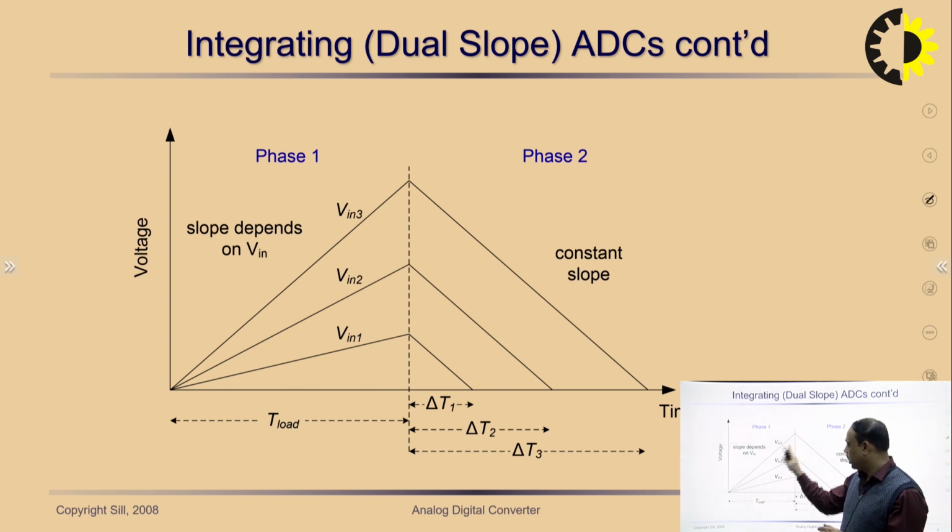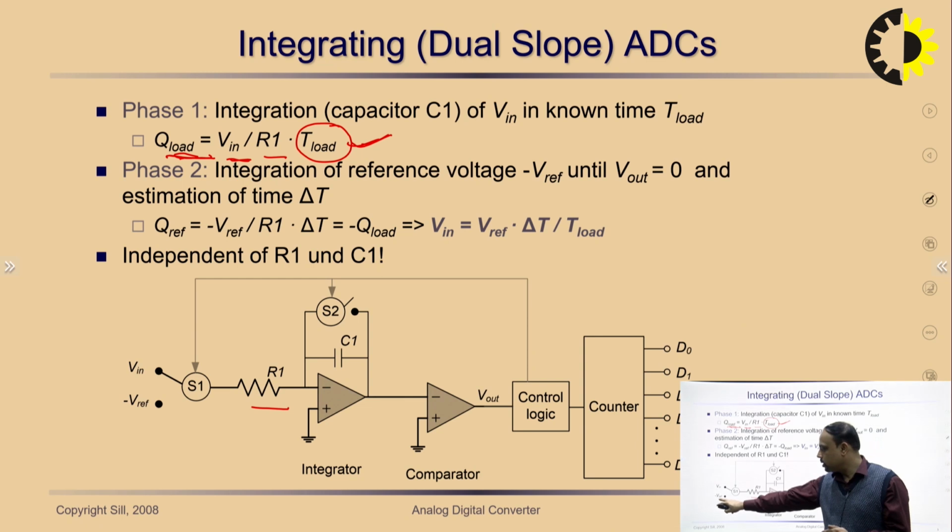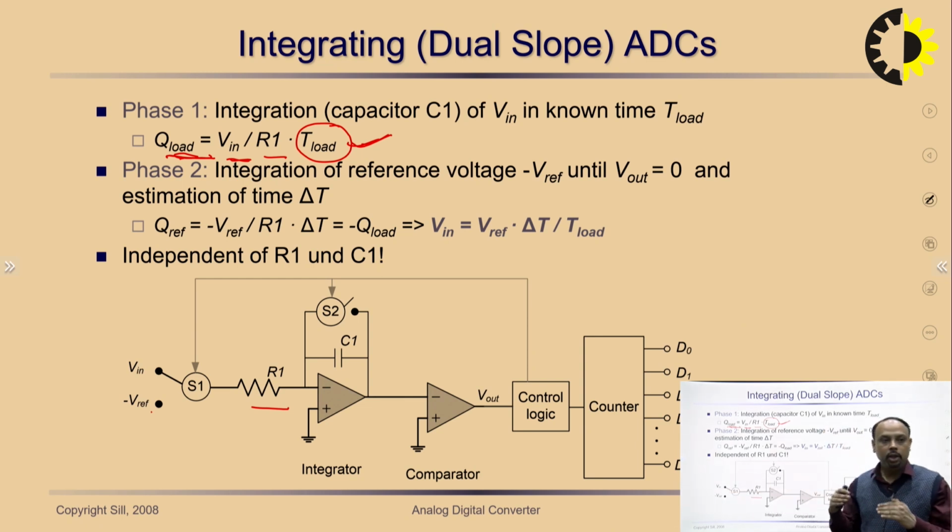So at the output of the integrator, we have a fixed amount of voltage. To convert this voltage back to the reference zero voltage, we need a negative polarity of the input reference voltage, so that the magnitude now goes down from a fixed value to a zero value.